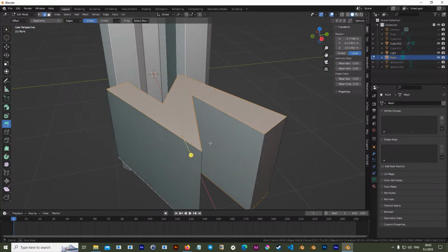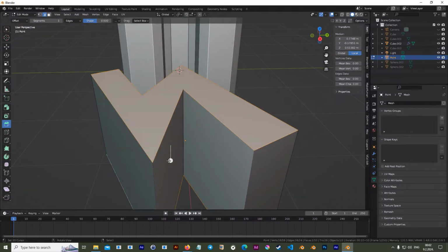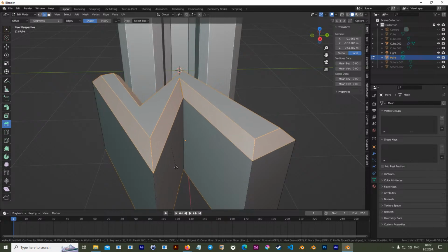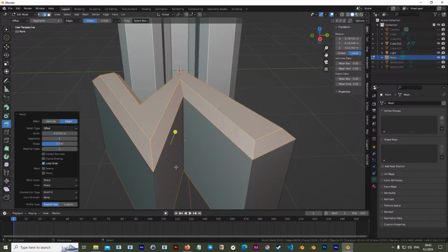Undo it. Let's not forget one thing with bevel. Bevel operations you do on your object in edit mode. Once you've done it and left the mouse, it's not something you can do again with your mouse. You have this little black dialog. Once it's gone, it's gone. The bevel is done.